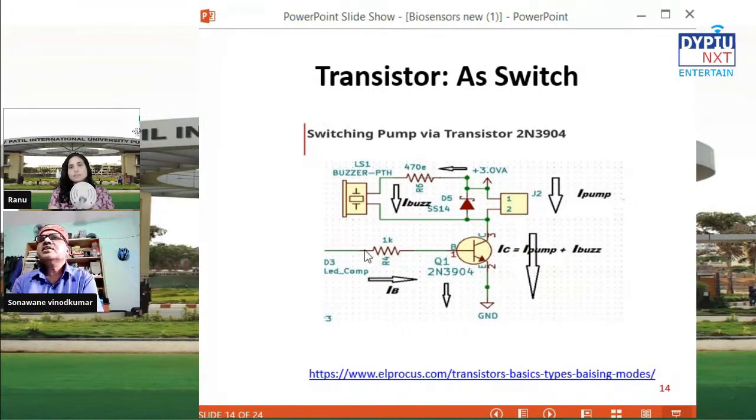But let me say that suppose in the transistor, if you give any input to the base, say B1, to my left, then you will get IC at the collector side, and to the collector you can connect any relay or any switch, and you can connect that relay to further devices like a motor or any centrifuge, water pump, which can be controlled with the transistor.